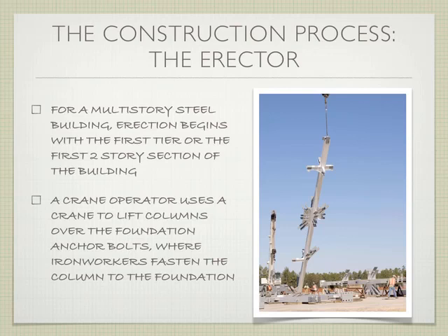So they're not bringing just the column to the site and just the beam. All of these are special plate connections that are welded, and they're going to eventually have diagonal braces attached to them, etc. But all of this welding and this intricacy is done at the fabricator, and comes to the site already assembled like this. So you don't have to do this on site. That's the important thing.